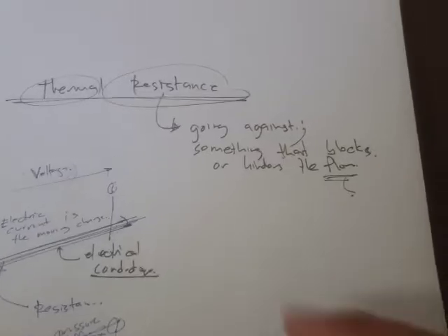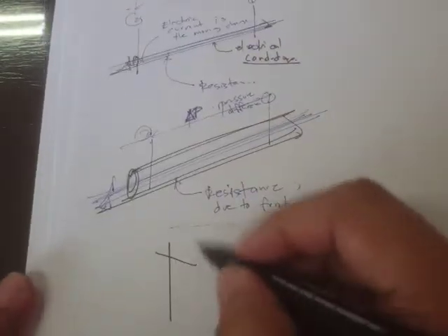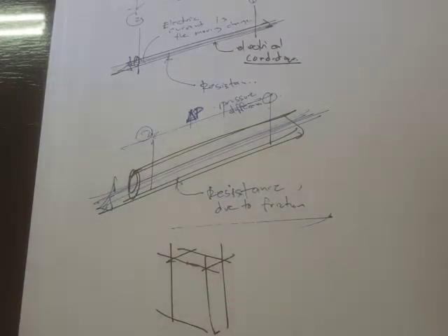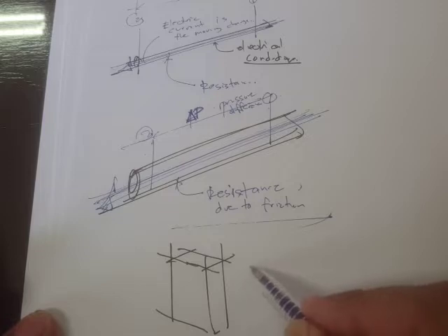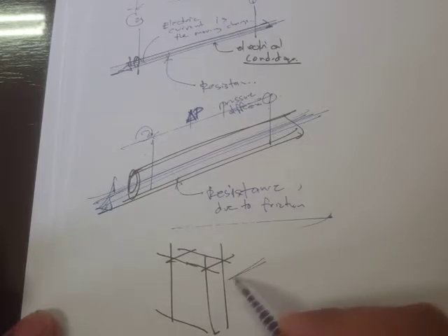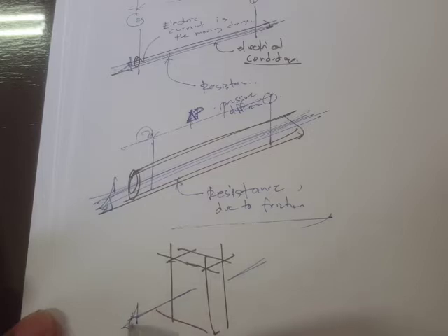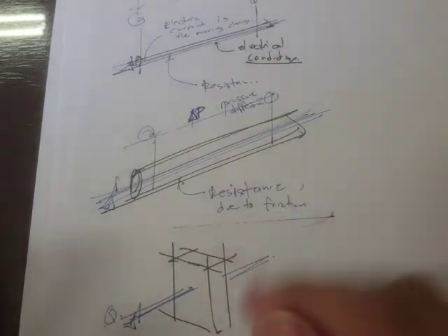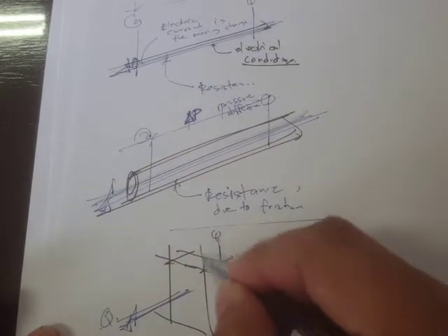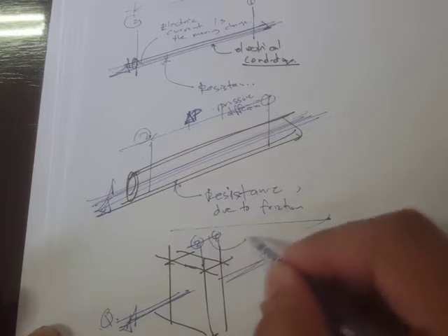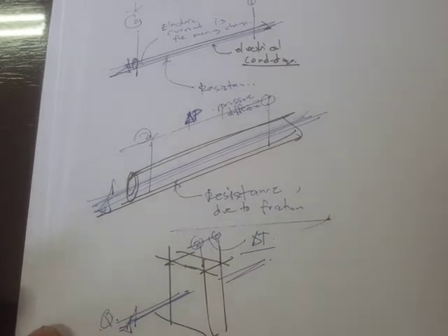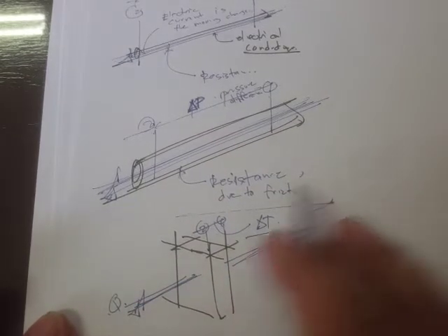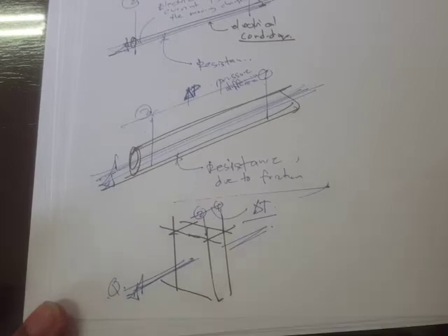Now the same goes true for heat transfer. Let's consider conduction heat transfer for now. Let's say we have this material, and there is a heat flow that occurs. Right, so here's our Q, from this direction to that direction. Now, in order for the heat to flow from point 1 to point 2, there must be a driving force, and the driving force is the temperature difference. And as the heat travels from point 1 to point 2, it actually experiences resistance.